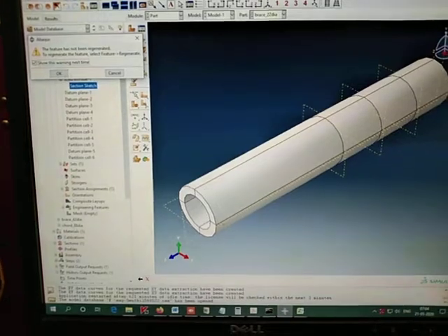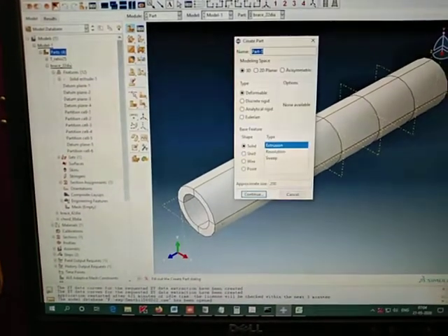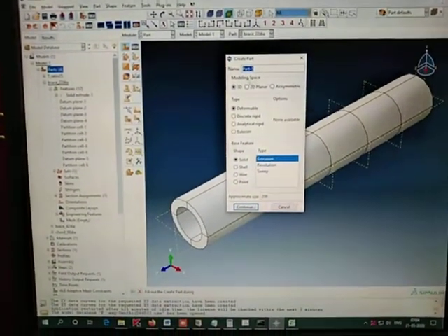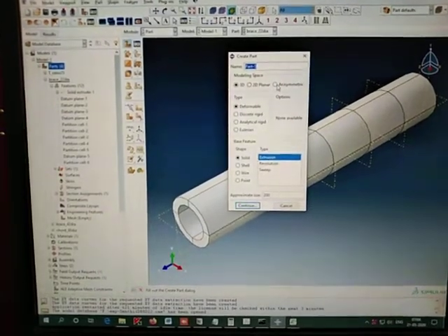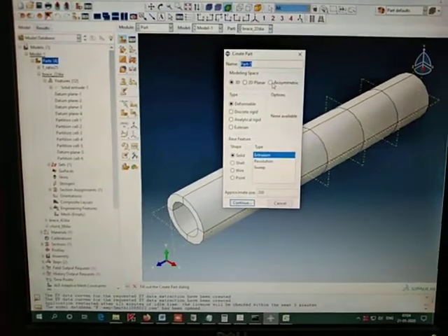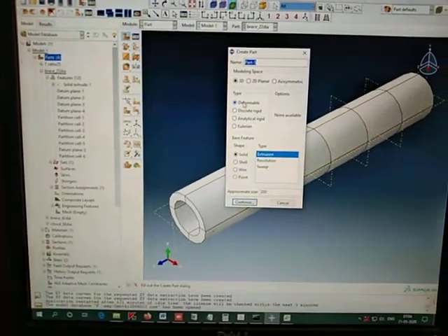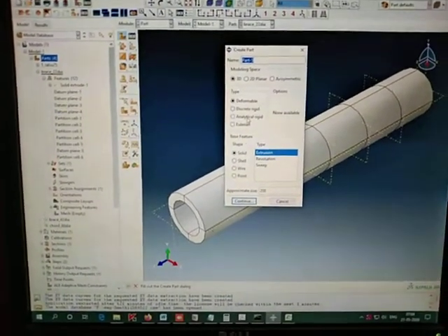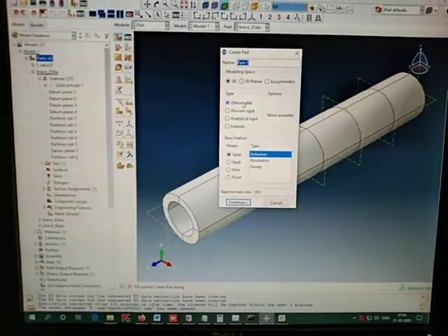And the most important thing is we need to be precise in choosing the properties. Under this create option we will be having this set of variations for 3D, 2D planar, axisymmetric. Axisymmetric is used for bolts or some repeat where the axis symmetry plays a major role. And this deformable or discrete object, analytical rigid, we are not going into it. We are just using this deformable for these solid steel structures.